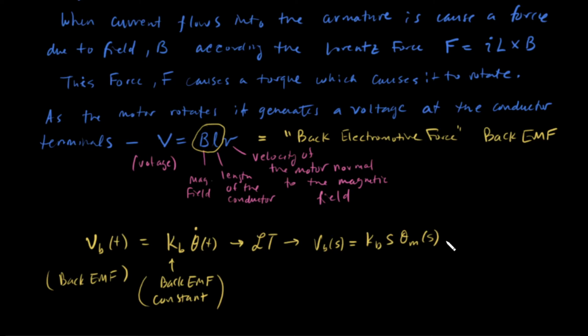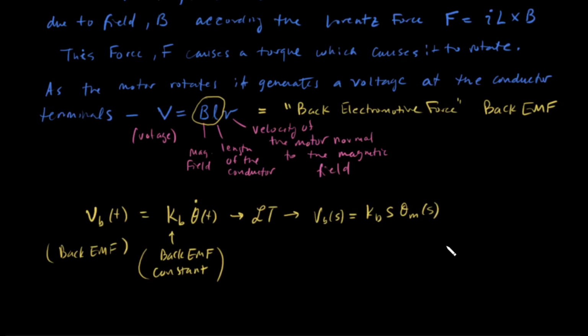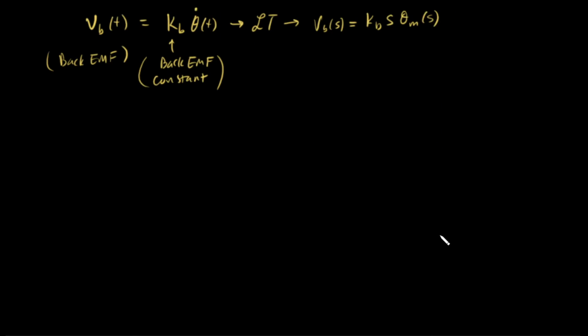We already know how to model the dynamics of the circuit, so let's just do that. If we have a circuit here, which represents the motor, this is where you would connect to the armature, and inside of the motor we have the coil. The coil of the motor has some resistance, R_A, which we'll call the resistance of the armature. It has some inductance, usually it's really small, we'll talk more about that. We'll call this the inductance of the armature. And then it comes down here, and this is showing the motor diagram, which in this case shows the brushes of the motor.